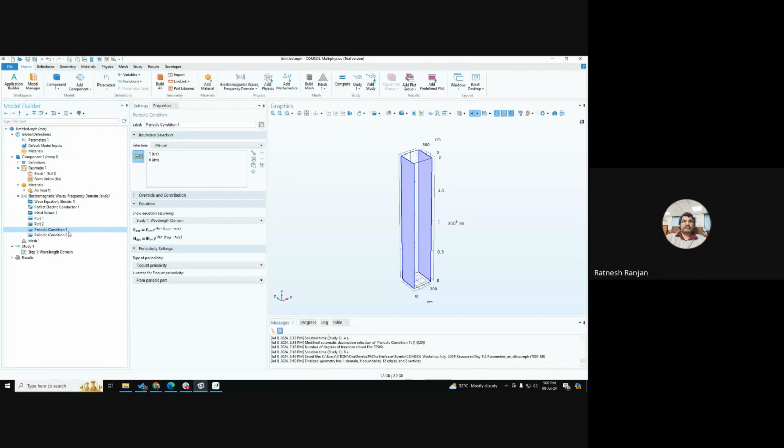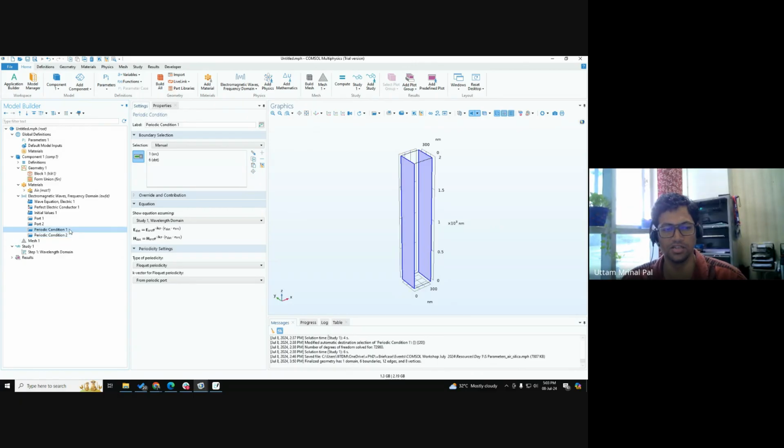Yes, in microwave studio CST and Ansoft HFSS, we mention Floquet boundary conditions and define which boundary condition, like master and slave, and the direction of the electric and magnetic fields. Yeah, it's the same as master slave. You can see source and destination here. The source is the master and the destination is the slave.